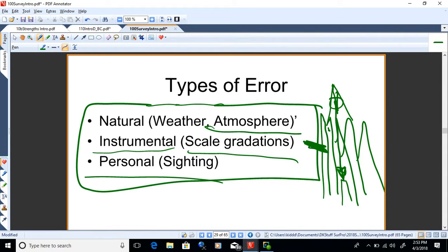Sometimes they swing left, sometimes they swing right. So I try and sight down the middle, which I guess you'd say kind of near the top. Yeah, near the top, okay? That's how you try and compensate for that, okay? But if it's a windy day, it's probably going to push that plumb bob over a little bit. You got all sorts of stuff going on here. So surveyors want to know about this stuff and compensate for it.